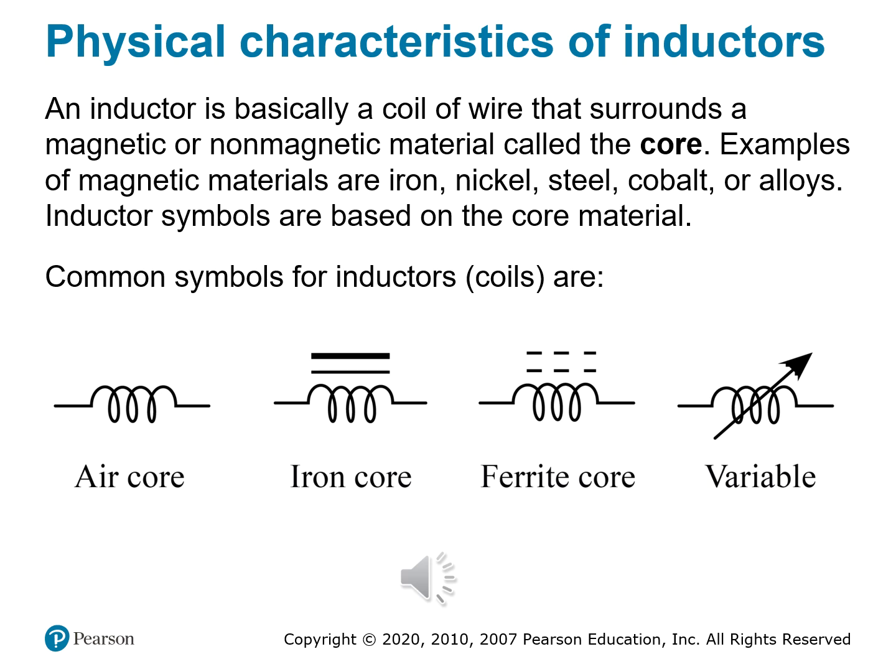Each core material gives the inductor a different magnetic permeability, and that affects one, the amount of energy stored, two, the frequency range it works best in, and three, its resistance to saturation under high current. So the next time you see a coil on a schematic, check its symbol. It's telling you exactly what kind of performance to expect.